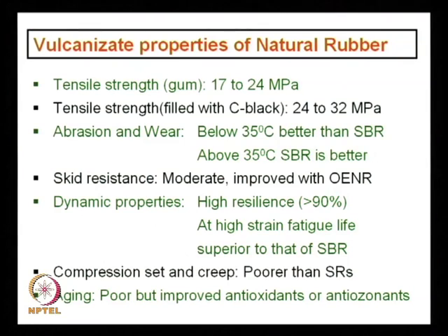Okay. And relaxation, it is again a time dependent phenomenon. It is the decrease of stress with time at constant strain, due to loosening of the molecules, due to relaxation of the molecules. Again, here is science, beautiful science. If you want to know, knowing that science, you can correlate these creep properties, relaxation properties. Aging, poor, but improved antioxidants can